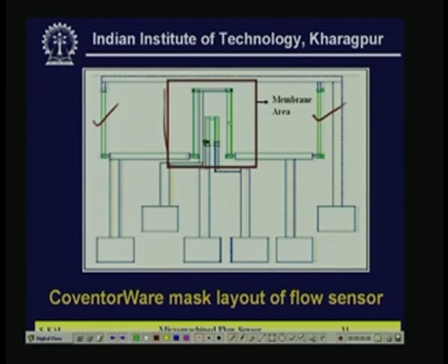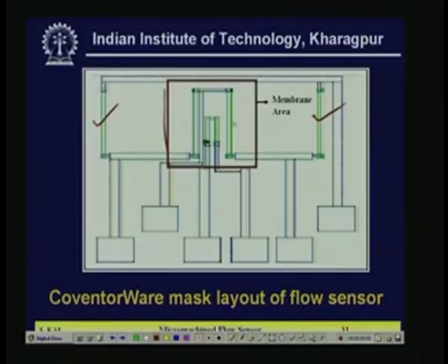So, you will get much more sensitivity if you can make the sensing resistors very close to the heater. Now, another structure may be thought of. There you can have a meander line resistance, so that the total surface area of the resistance is more, so that the change of resistance due to the heat absorption, or the fluid flow converted into heat, will be much more effective. The heat change will change the resistance, and that can be done by using meander line resistances.